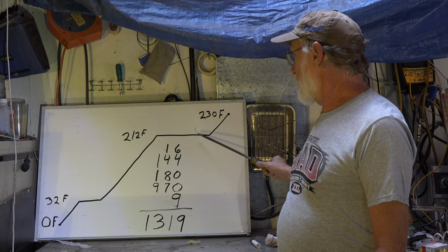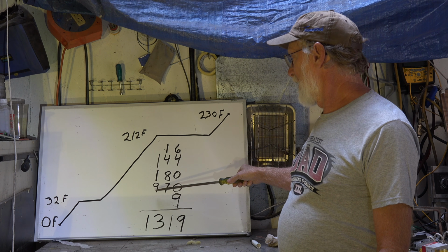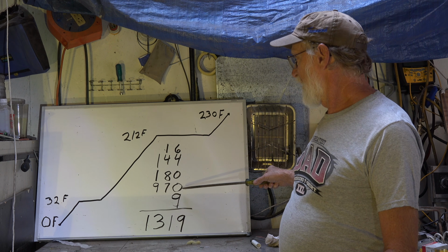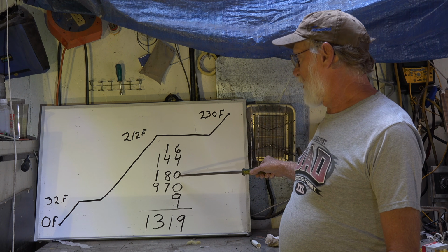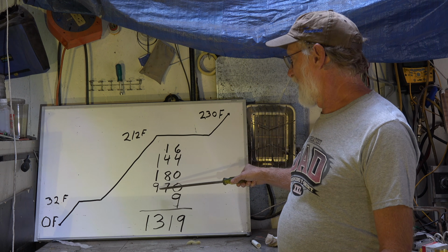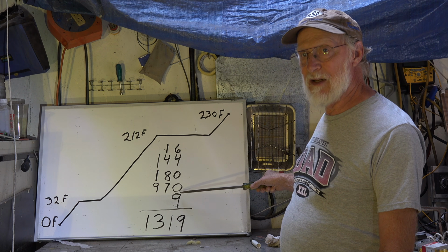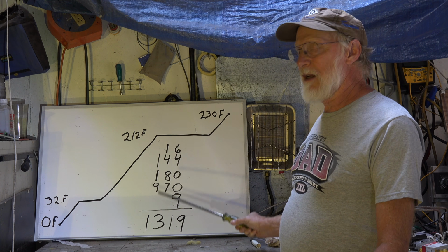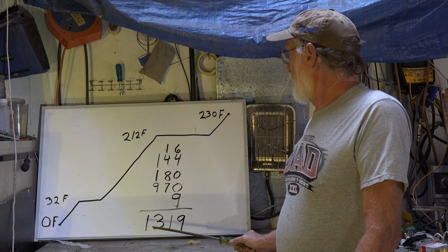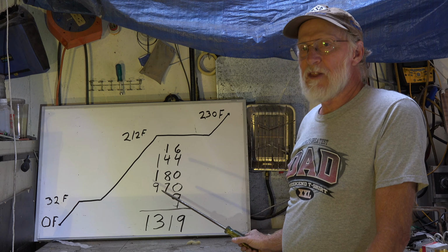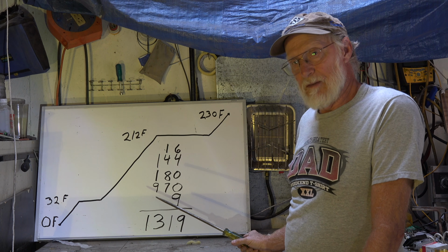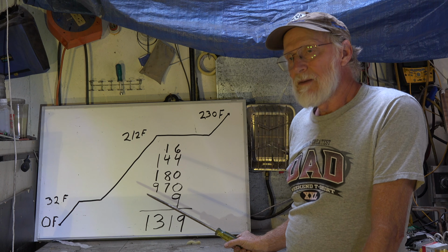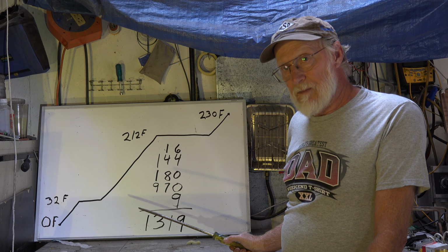So it absorbs BTUs. Now this is the big one, 970 BTUs. Took 180 to get it up there of sensible, but it's taking 970 to turn it into steam. That's the big one. Okay, my final temperature here is 230 degrees Fahrenheit.